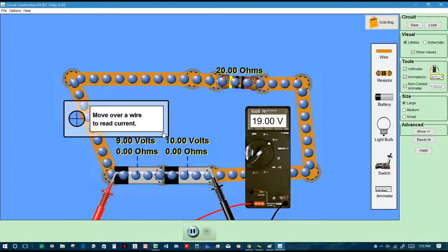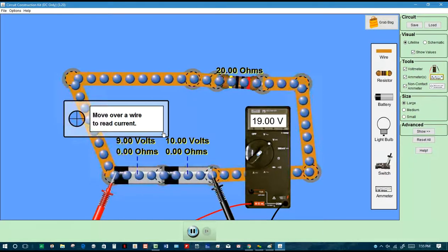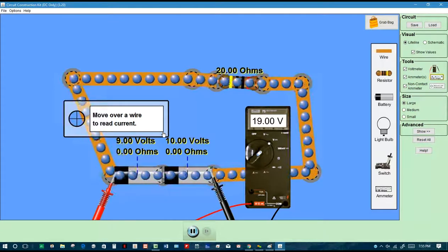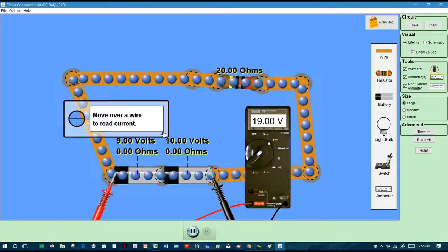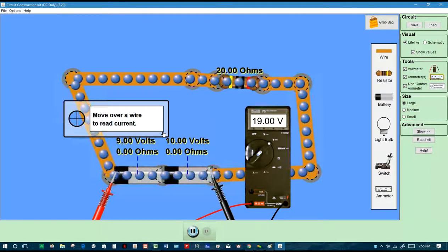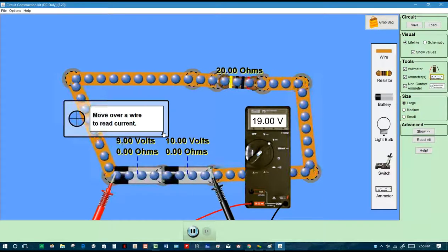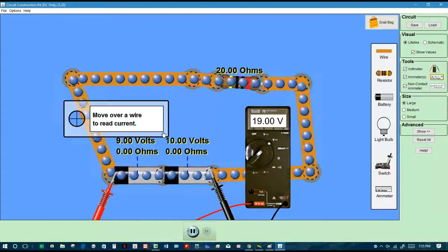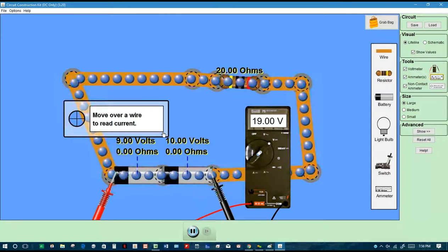Because in number 2, your homework problem, notice it says 4 1.5 volt cells. When they say cells, they're referring to batteries, connected in series. And what I'm showing you in this picture on the app is that those 2 batteries are in series, just series means one after the next, right? And you're seeing that the voltages add. So with all that I've said, I think you're ready to try number 2.